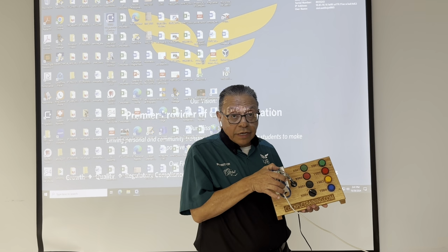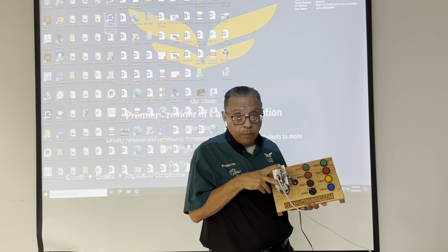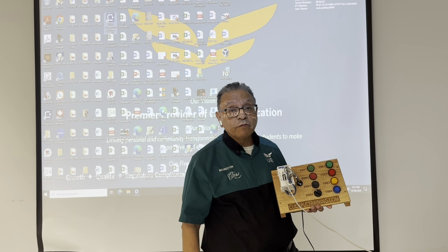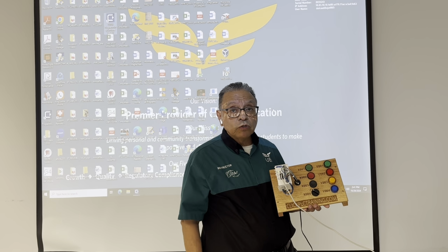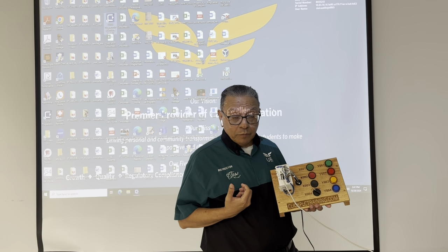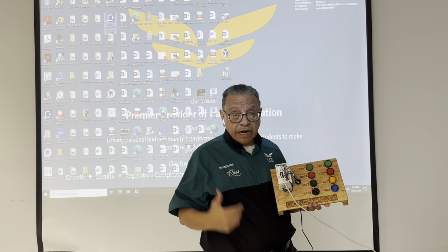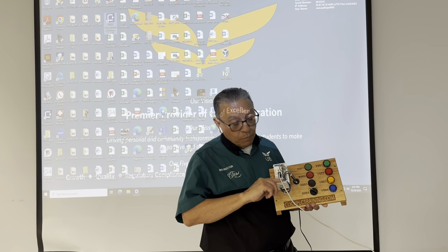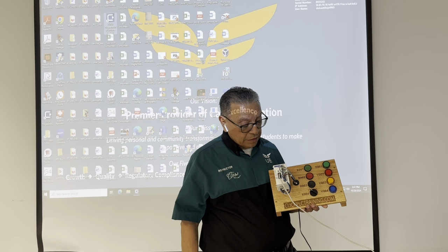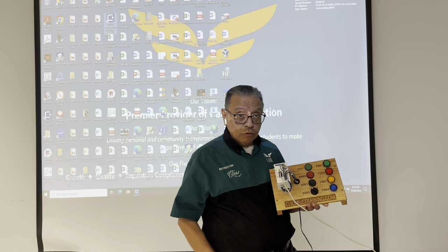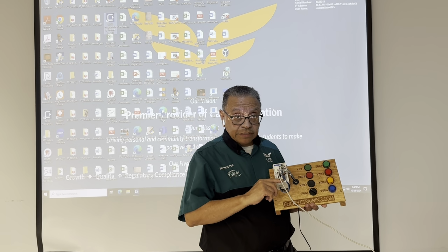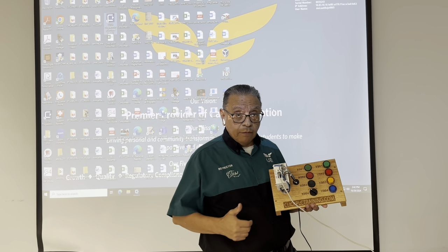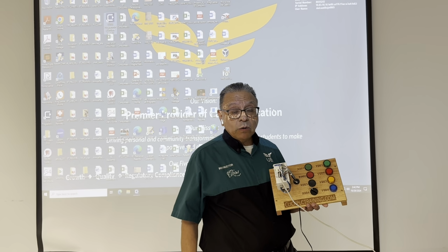And right here, this connector, this is a terminal block, and behind this we have the input interfaces and output interfaces. The upper section is used to collect the information from the input devices. At the software level, they are represented by the letter X. At the bottom, we have the output interfaces, used to send information to the external world and to control electrical devices, represented here at the software level, as you will see, by the letter Y.